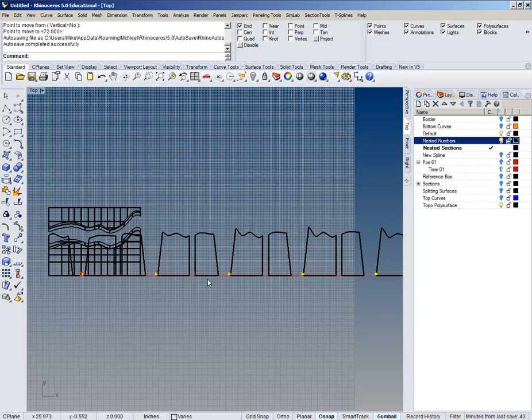The Corel will take almost anything. It'll take a PDF, it'll take an Illustrator file, it'll take a DXF or anything. Since this is just line work, it's easy to just do this as a DXF. We've only got 2 layers. We've got an etch layer and a cut layer, right? That's all we got. It's not going to different depths and things like that.